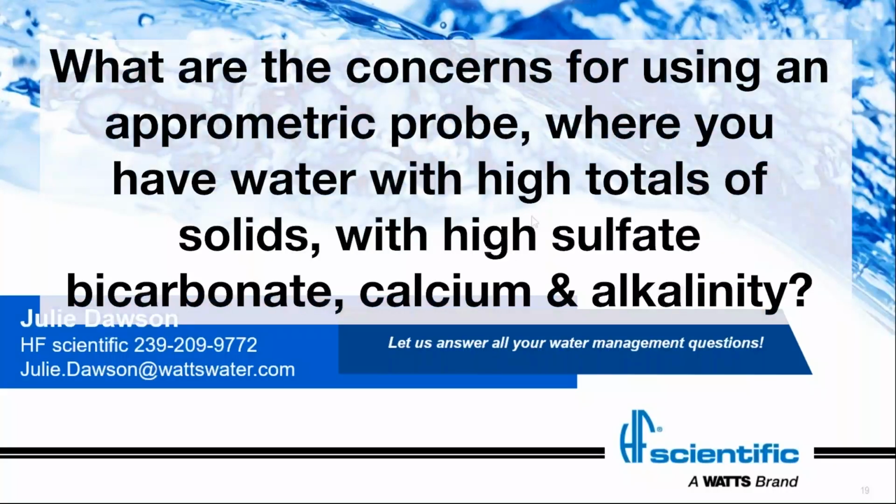You know what? I'm glad you brought this up because I should have included it in my presentation. So in general, if you have high hardness applications, you can often have maintenance issues with the probes because they are membrane probes. So you can have scaling on the probes, you can have fouling on the probes. And so high total dissolved solids, if they settle out in these smaller measurement chambers, can scale over the probes and cause inaccurate readings with amperometric.